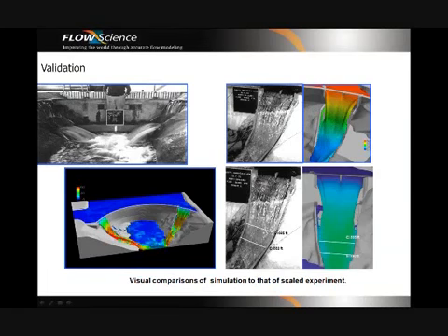Starting with as-built drawings that AEP provided, Alden used third-party CAD software to create solid models for import into Flow3D. They then meshed the model in Flow3D as a low-resolution model, a medium-resolution model, and a high-resolution model at 13 million computational cells.